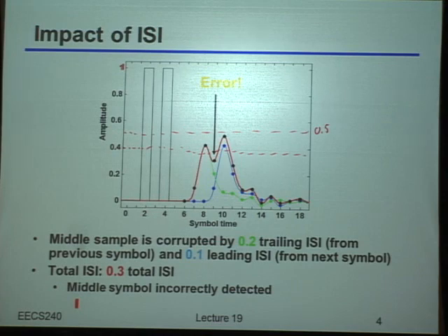But it wouldn't change the fact that, for example, this piece of the green bit is messing up that piece of the blue bit or vice versa. Okay? In other words, scaling the transmit swing, if you have an ISI problem, really won't solve it. If you're already making mistakes due to ISI, you can increase the swing as much as you want. It's really not going to solve the problem.